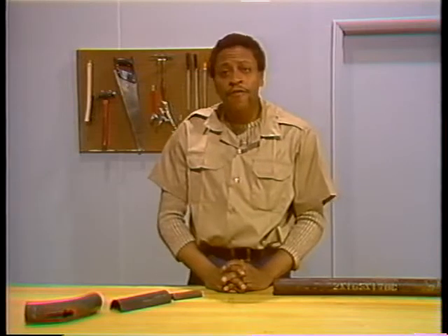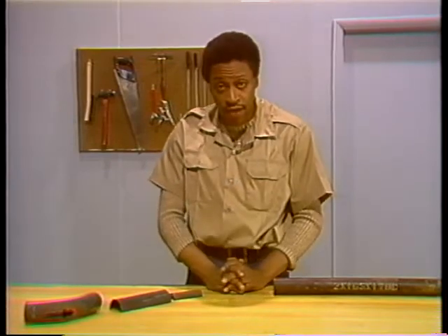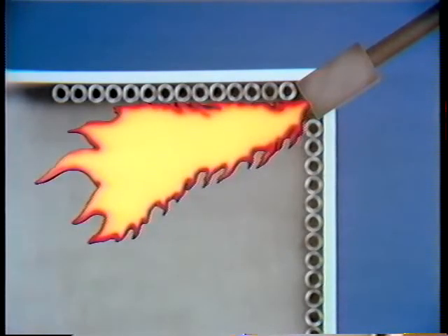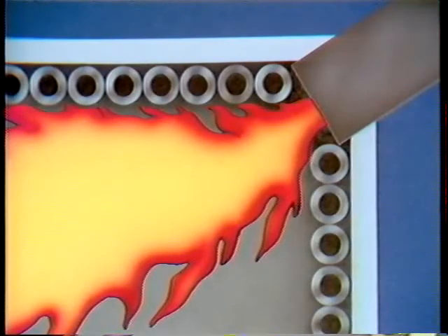Overheating from improper flow of hot gases happens when the tubes are exposed to more heat than the normal cooling flow can handle. One example of improper flow of hot gases is flame impingement. Flame impingement is direct contact of furnace flame with the tubes. When flame comes in contact with the tubes, it can raise their temperature so high that they fail.